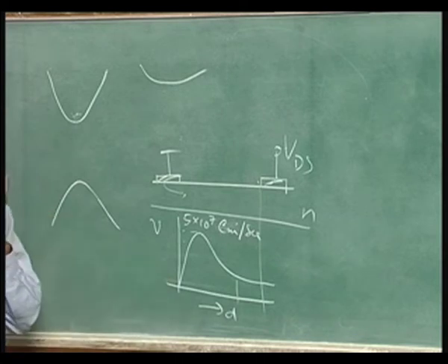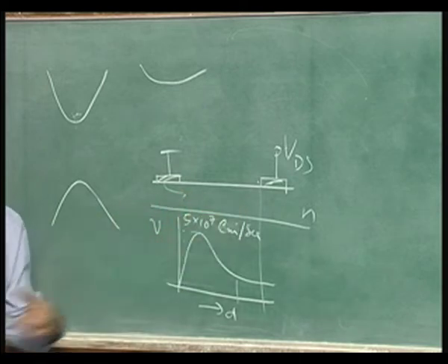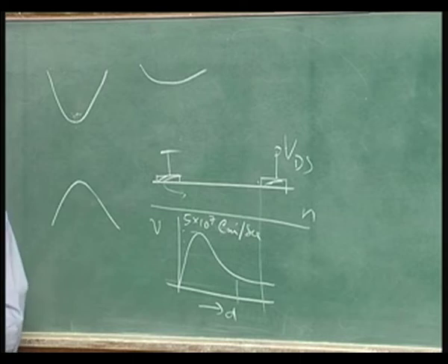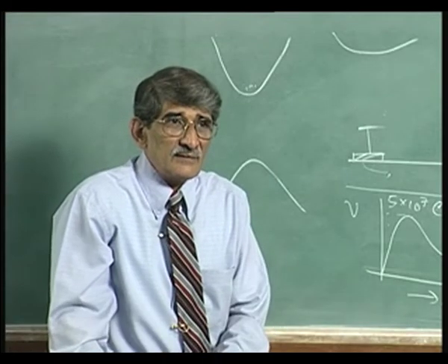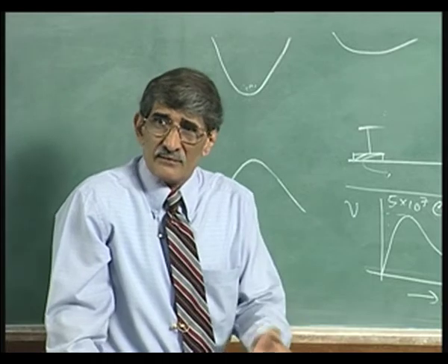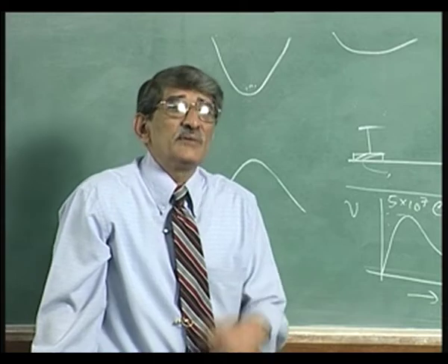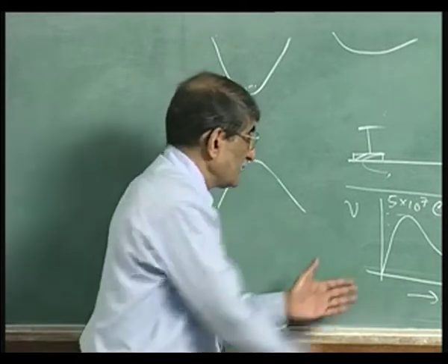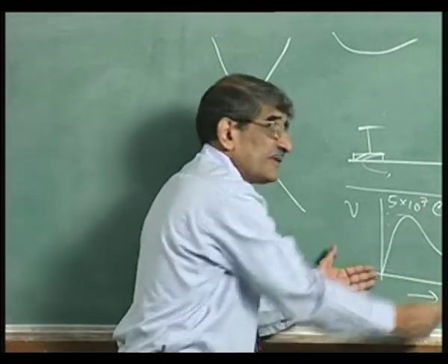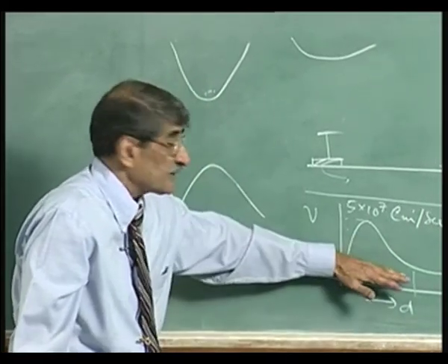Suppose I move it here. Now, you can see where the impact of this velocity overshoot effect is. Make the channel length shorter. This exactly works out against the belief of people that short channel effect devices, gallium arsenide, will not give the benefit, because they were fearing that the velocity saturation Vs is almost the same in silicon and gallium arsenide. So, when you go to short channel devices, you will not have any benefit, but now you can see in the initial region of 0.5, 0.6 microns, you will have velocities much higher than saturation velocity.